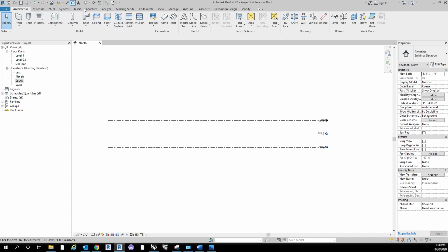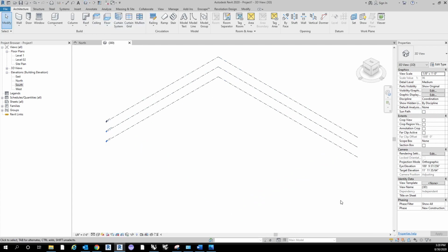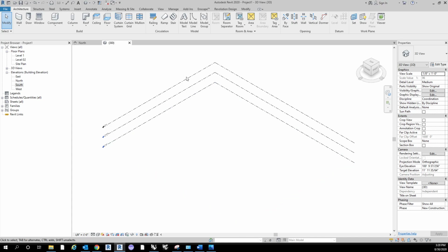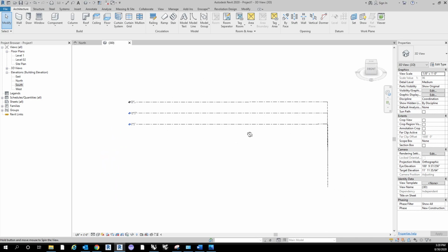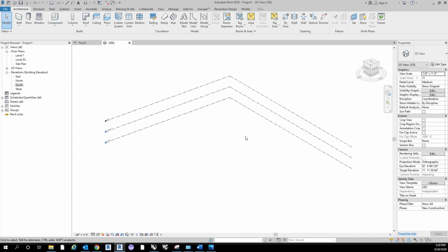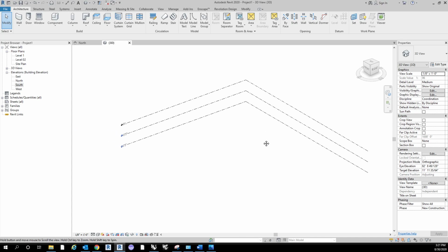And then your measure tool, align tool, and then this is your default 3D view, which I use a lot. If you click that, it'll go to your typical 3D view, which you can then use to pan around. To pan in the three-dimensional space, what you have to do is hold Shift and then right-click and hold, and then you can pan around like so. And then to pan two-dimensionally, just back and forth, all you have to do is click and hold the mouse scroll button.